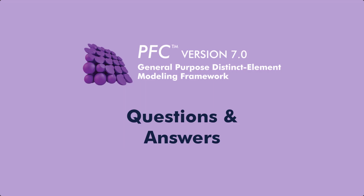So you could say this is a cut face against a cut face. A contact's created, you could catch that contact creation event, and then if you so desired, you could go and specify the forces explicitly for that newly created contact between the two cut blocks to be what you thought was appropriate.